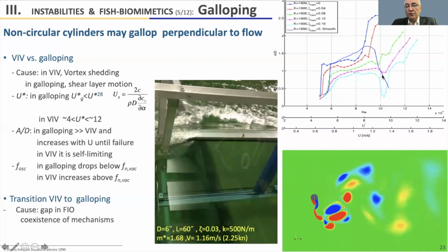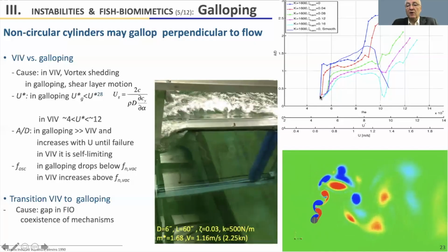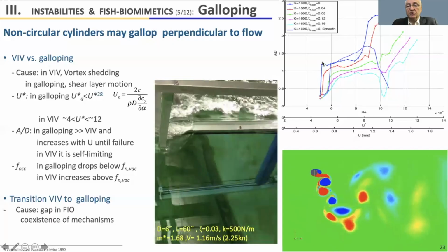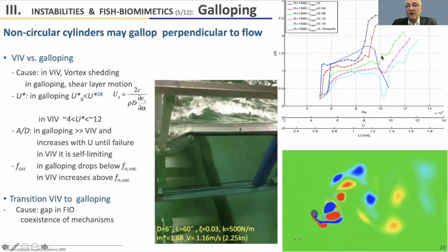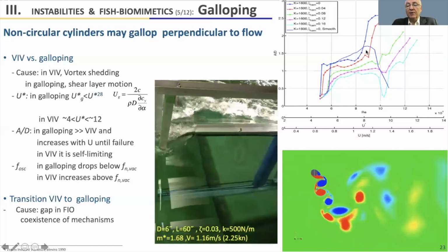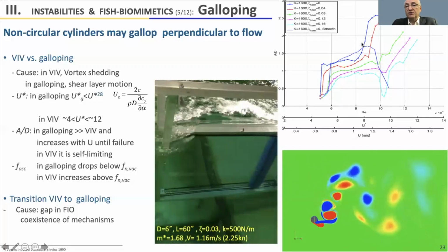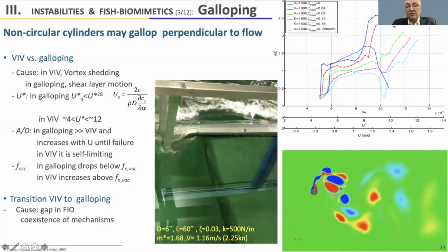Of course, if you put them back to back, then you see what kind of a response amplitude operator we have. It starts a little bit before the natural frequency of the oscillator in quiescent water. And then you can move galloping, as we will see later, a little bit to lower velocities and have an open-ended response amplitude operator.